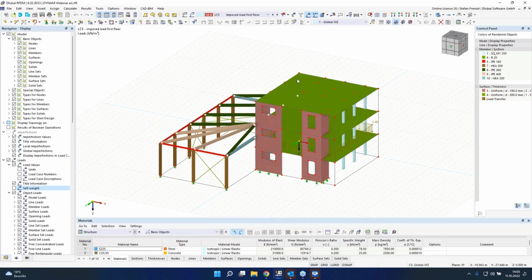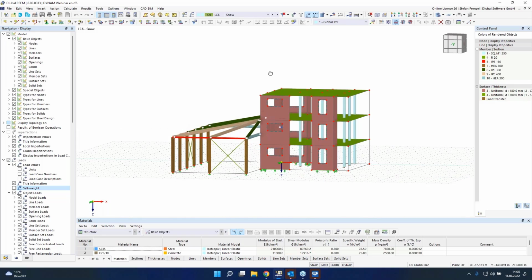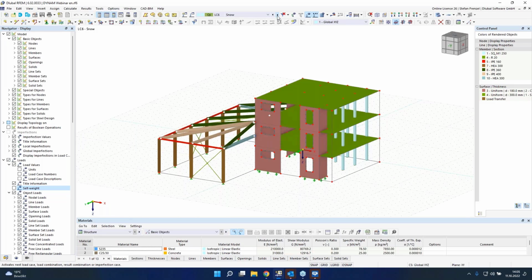These loads we want to use also then in the modal analysis. And of course, you see here a snow load, which looks empty, okay. And yeah, we can create a snow load, that's no problem. And of course, a wind load. For the wind load, you see that we have here already a surface load, which is applied here on this opening.